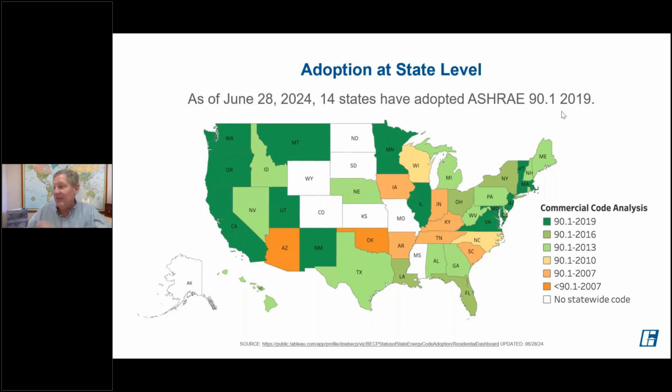The other thing we should be aware of is I believe Massachusetts does not use 2019 or 90.1. They use 189.1 in IGCC, the stretch code. Basically, everything in 189.1 is 10% more energy efficient than what's in 90.1. So that's something else we should be aware of for Massachusetts. We'll talk about that a little bit more going forward.